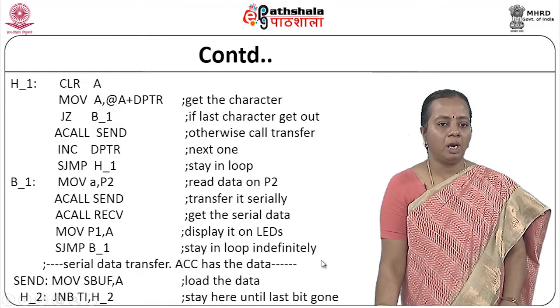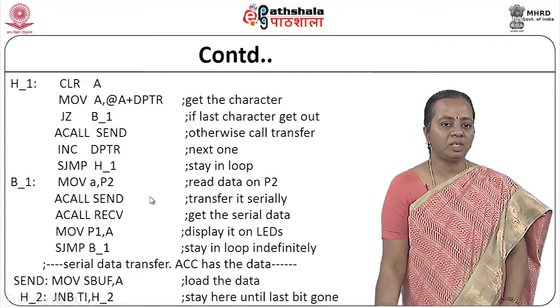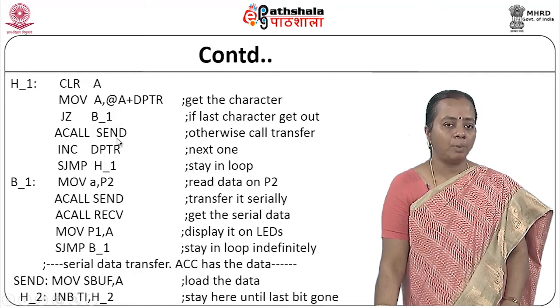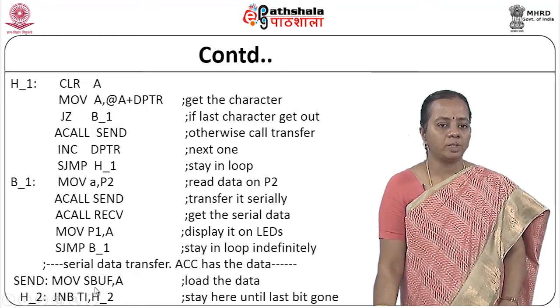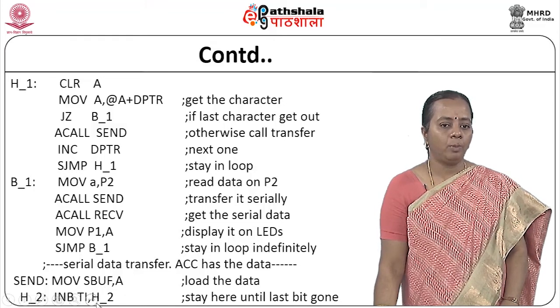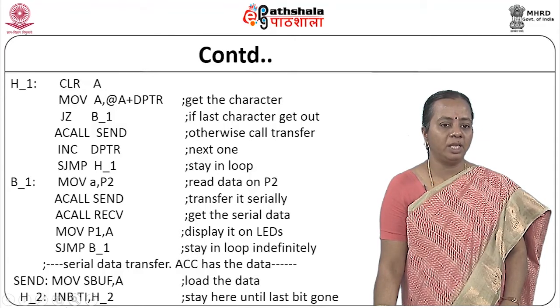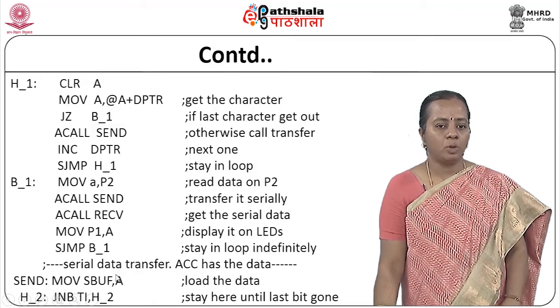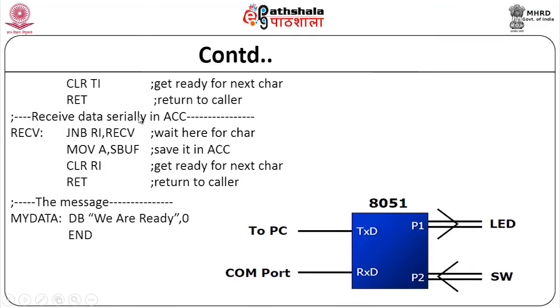Now we see how it has been sent. Send is a serial communication subroutine. So now you just see that MOV SBUF, A. Whatever the content of A is moved to SBUF. Now I am monitoring JNB TI. So I will be looking at whether TI is equal to 1 or not. Till then I will be looking again and again. So once it gets a 1, then I will clear it and I will return to the caller.